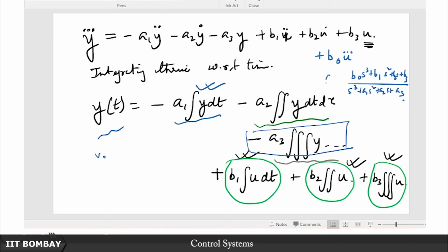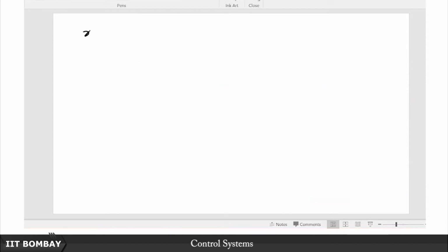Yeah. So you can have a transfer function like this after all, right. Notice all we have said is that it cannot be improper, but a transfer function can be biproper. Now you might wonder, in that case, can we still represent a state space system in the form that we have discussed so far, that is, can we still have a state space description of the system given by this x dot is equal to Ax plus Bu and y is equal to Cx?